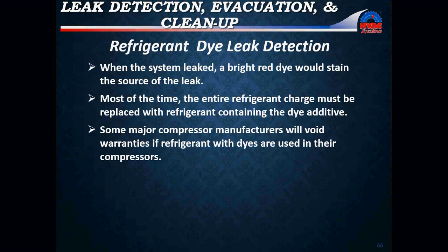So before you start inserting any sort of dyes to check for leaks, you want to make sure that you check the warranty of the compressor or of that unit to see whether or not it will void the warranty. Most refrigerant dyes contain a mineral oil base. Many HFC-based alternative refrigerants require the use of ester-based or alkylbenzene oils. Because of this, refrigerant dyes should not be used on ester-based or alkylbenzene-based oil systems.